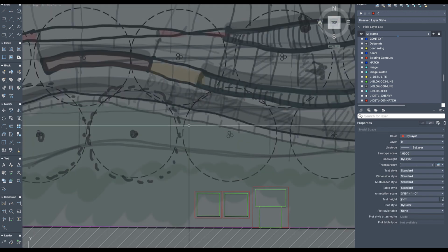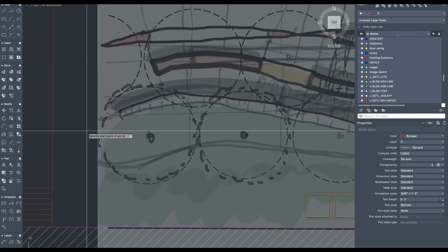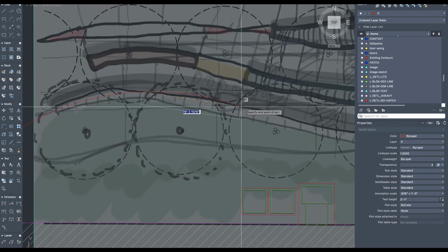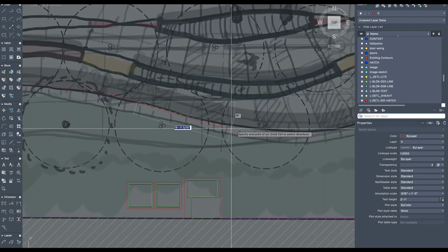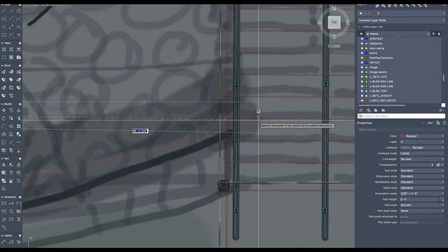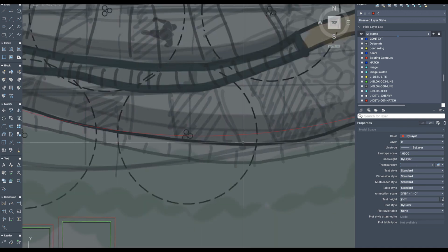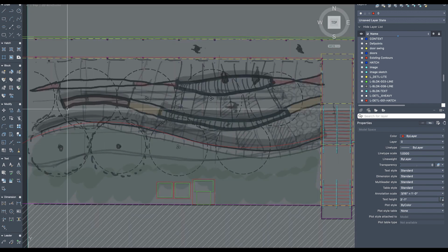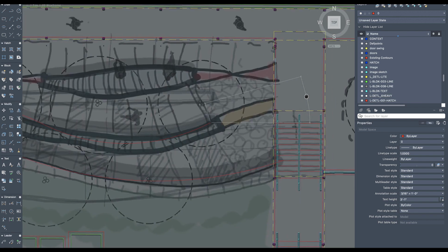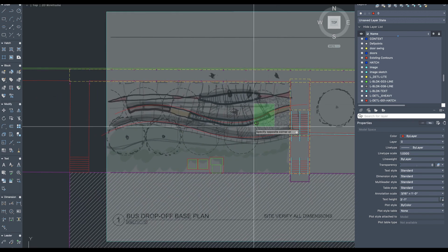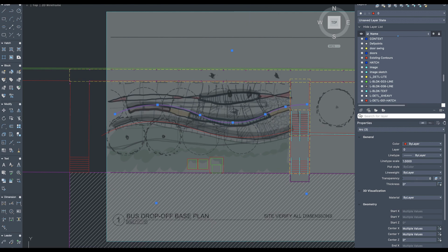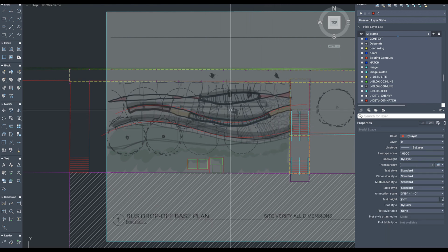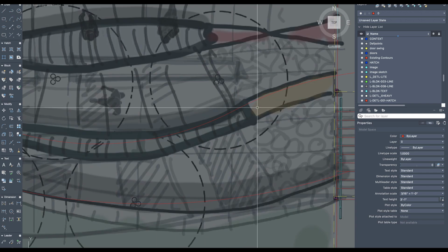Let's try it again. It's going to take a few instances, but we'll A space for arc. Click, click, click, spacebar, spacebar to recreate that next one and sort of send it over here. Now, this one's better, maybe, probably not. You're going to have to try a few different times. We'll do the same thing on this side. A space, here, here, spacebar, spacebar, here, spacebar, spacebar, doing it for this third arc right here. You're going to get stronger, more legible arcs. When you offset them, they're going to make more sense.